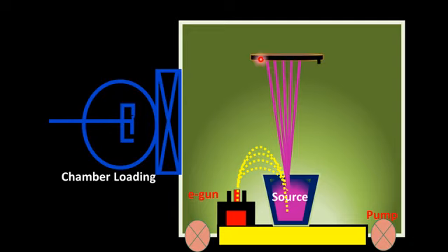These shutters are controlled by a microprocessor, and the precursor material is transported at a very small time scale. The shutter opens for a few milliseconds and then closes, so a very small amount of precursor molecules is transported onto the substrate surface. So the shutter in molecular beam epitaxy plays a vital role in controlling epitaxial growth layer by layer at the molecular level.